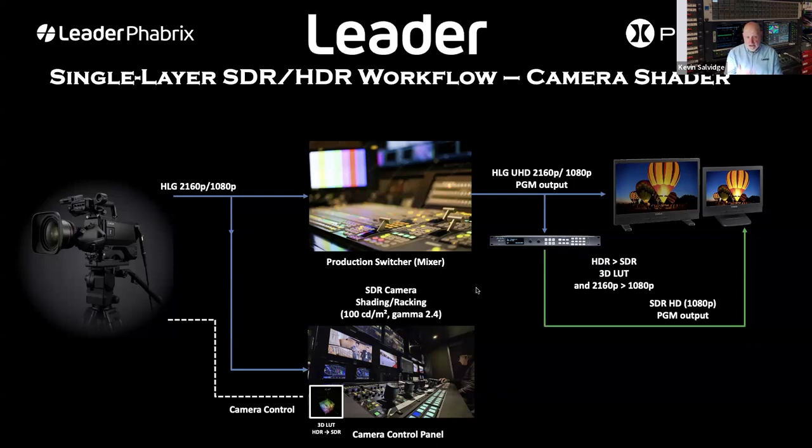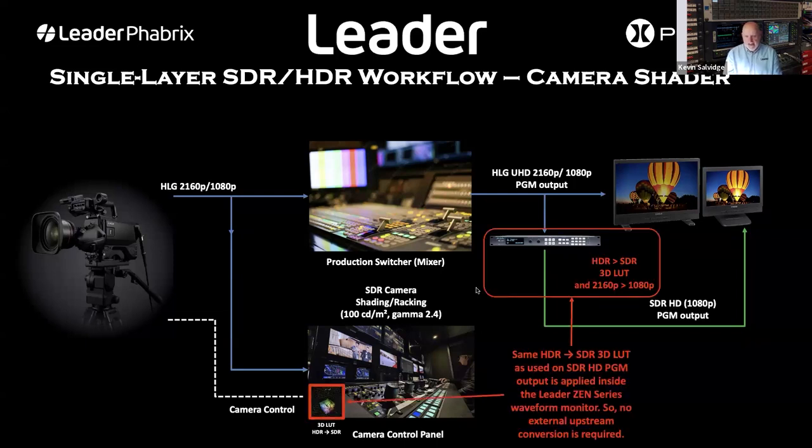So now you can see we've removed that conversion upstream. But the great thing is that now it is running exactly the same HDR to SDR 3D LUT that's being used to create the SDR program output. So what a vision engineer is seeing here is what the SDR looks like.